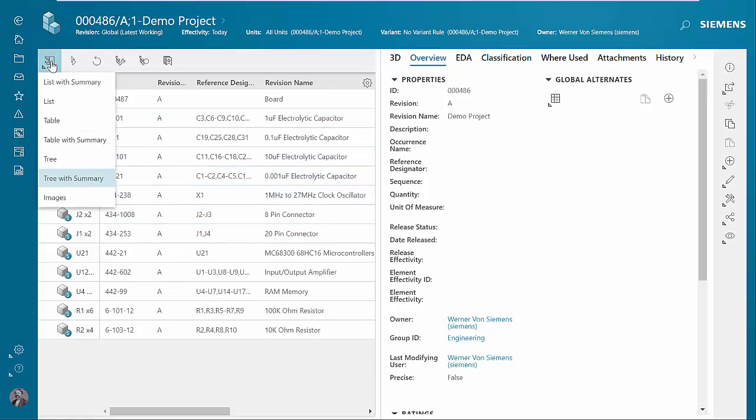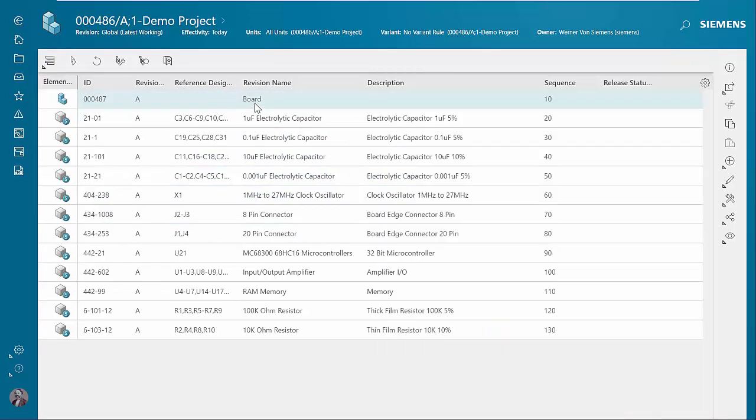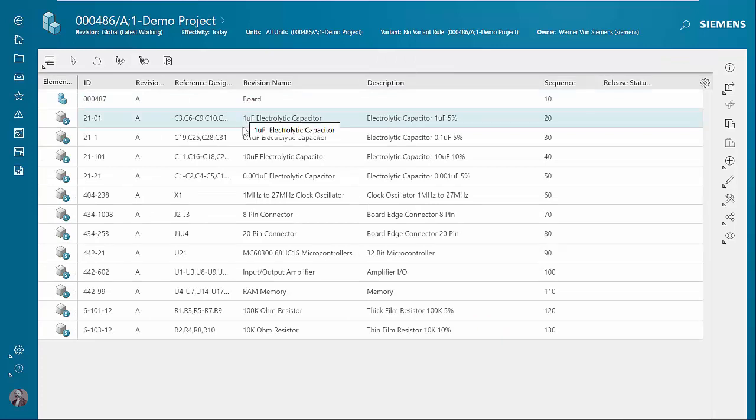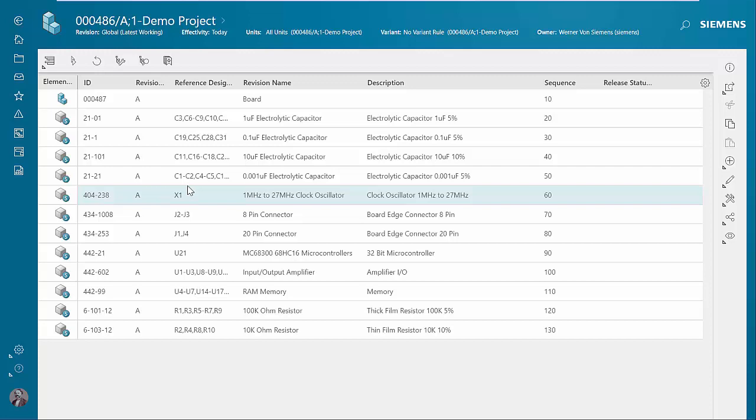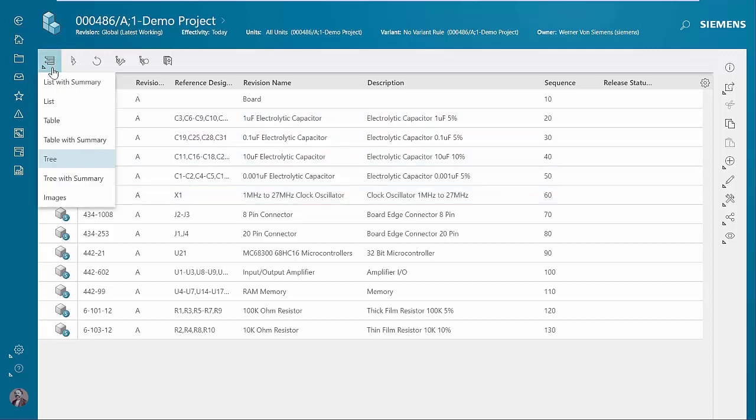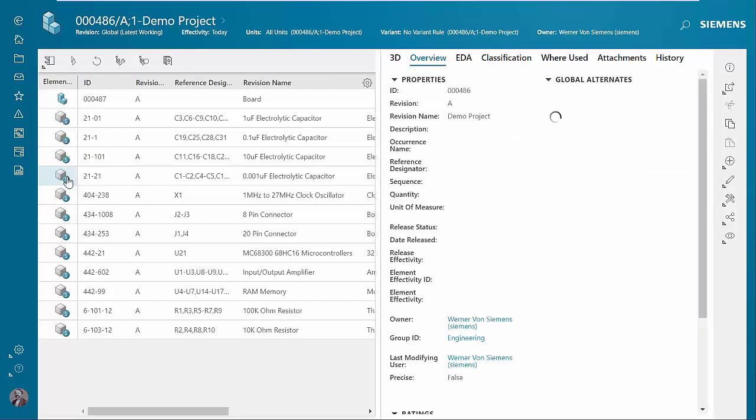We open the bill of material by itself. You can see the whole thing. See the board, which is the reason we pulled the board part number, along with all the rest of the part numbers included in this bill of material, along with the reference designators. And we're packing the reference designators as I'm showing multiple instances of a component in a single line.